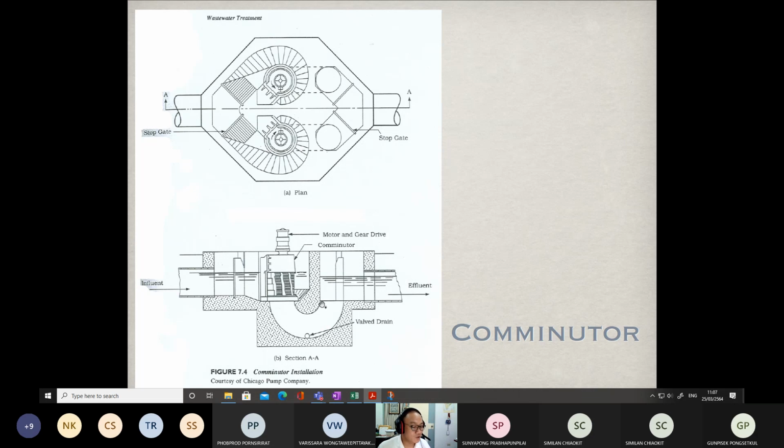We use a U shape to allow the water to pass through while the heavy particles accumulate at the bottom, so that we remove this accumulated material by opening the drainage valves, so that all the trash can be removed.